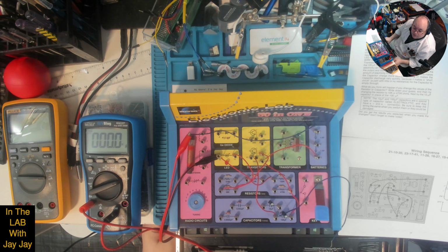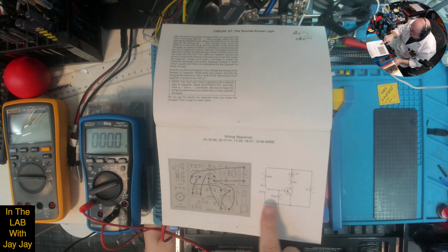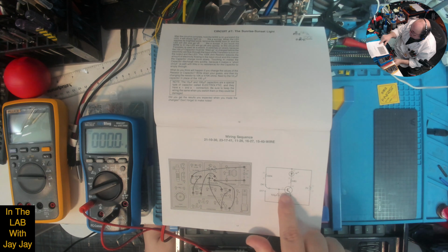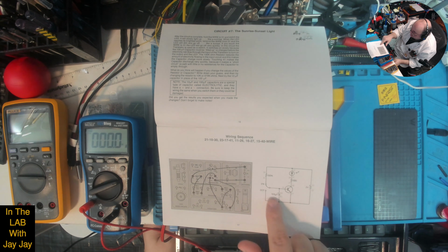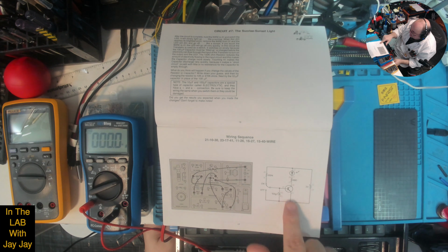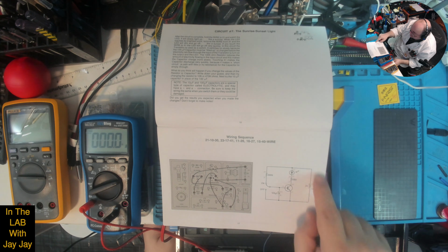Cool. So we checked the voltage, we checked the current. I don't think there's going to be anything to see on the thermals, so I'm not going to turn that on. Did we want to see anything on the scope? I don't think so. I think we know how this works. So from the top, when it's on, the capacitor soaks up all of the energy and doesn't allow anything through the base. But once the capacitor is fully charged, the power can run into the base, and then that turns on the LED.